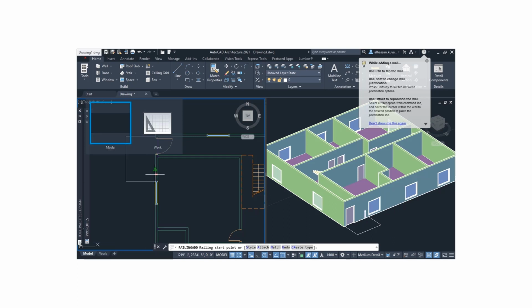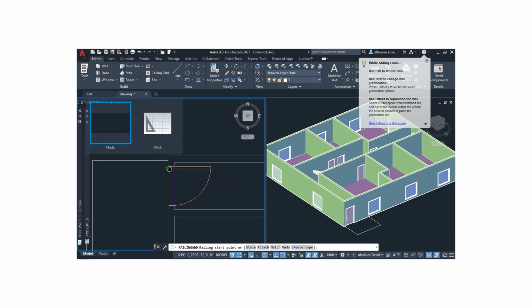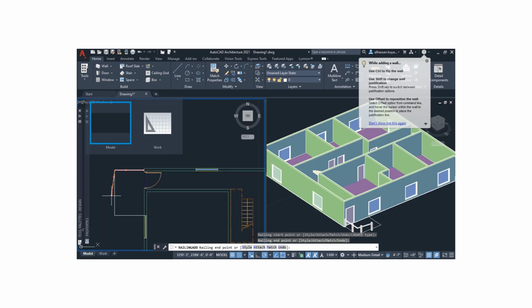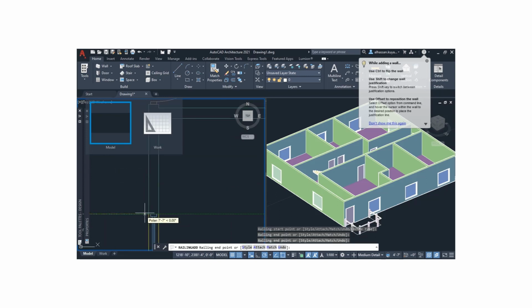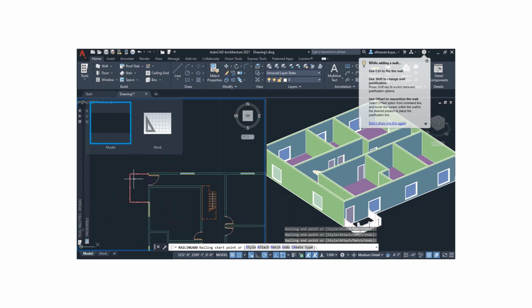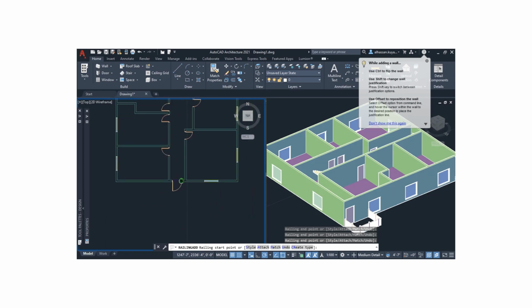The property is here. If we want to set it, we set it from here. Then we can draw over this line. So that's the first veranda, and we're going to create another one down here also. So we use line again. We want it to start here,